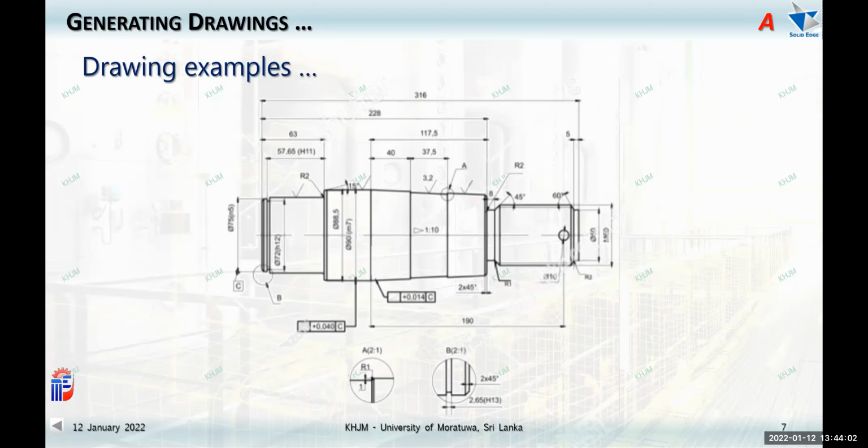That will indicate, so one is at B and the other one is at A. Usually you don't want to write the label, any texture here. Just you can say A or maybe detail A. Detail A. And also immediately within bracket you have to give the scale.